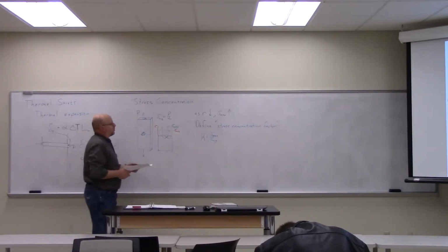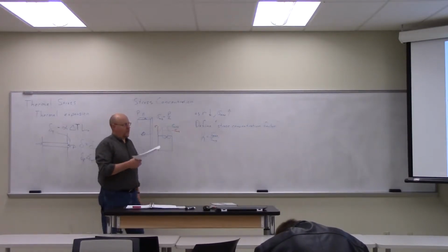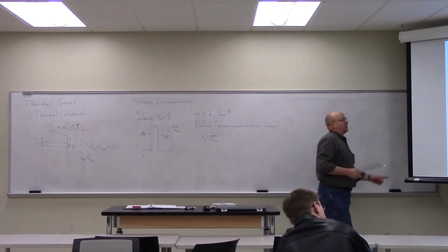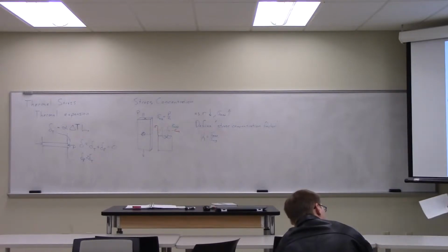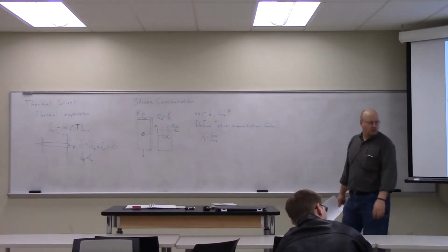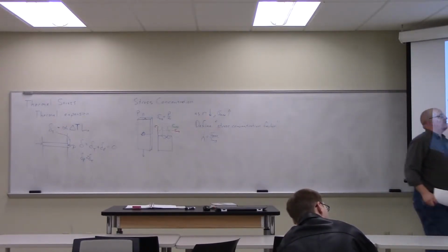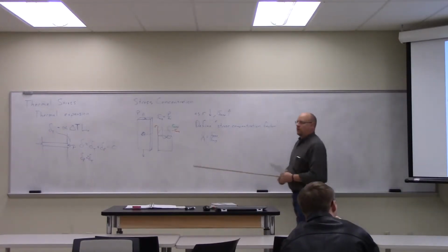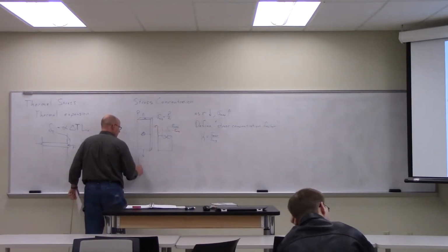And this is entirely determined by geometry. So if you look over on the screen over here, there are two ways you can concentrate stress. One is with a hole in the center, which is shown in the right graph there. So you have this configuration, or you can have fillets on the side. So instead of having a hole, you have a sample that looks like this.